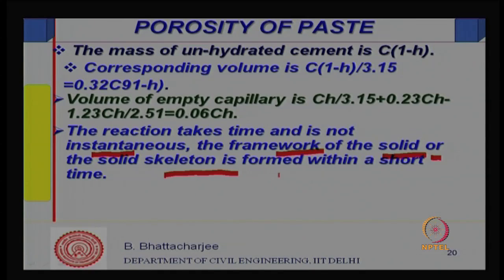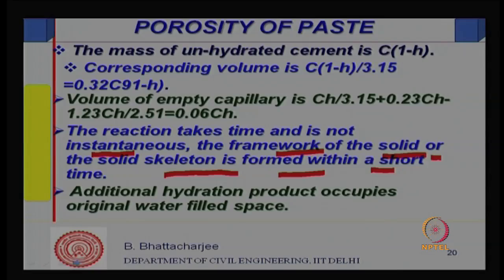Since the solid skeleton is formed within a short time, the rest of the hydration product occupies only the space available within that skeleton, the original water filled space.